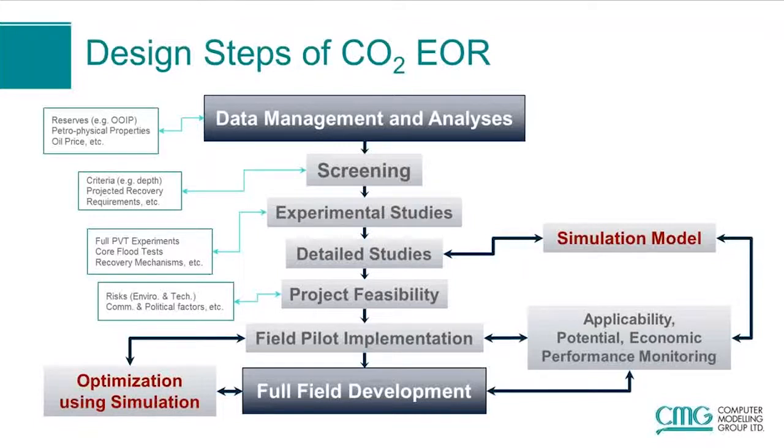The third step is experimental studies. The lab studies should be conducted to evaluate the performance of the selected EOR method, such as full PVT experiments and flood tests on representative cores to identify the recovery mechanisms involved in the process.